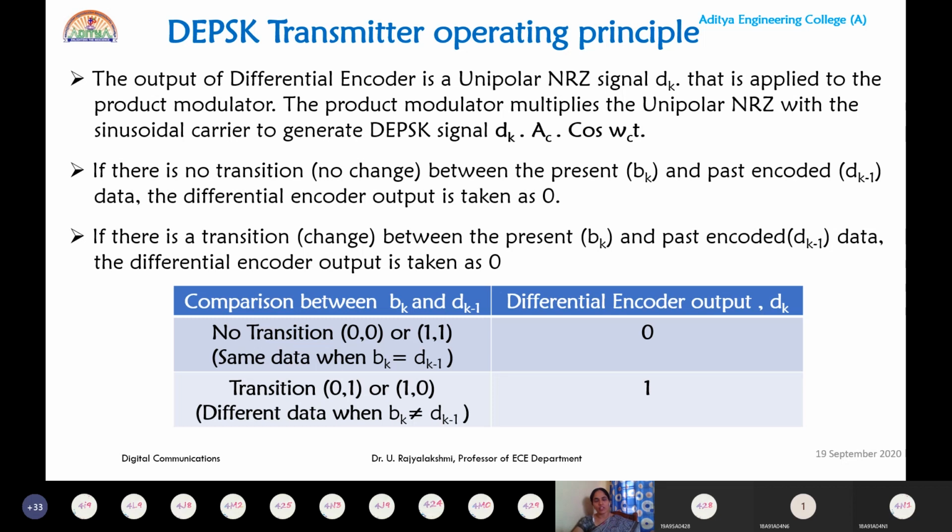So you may have a doubt about why we replaced it with the XOR gate, since we already have the XNOR gate. Because you can see the receiver. At the receiver also, we make use of one XOR gate to compensate for the XOR used at the transmitter. That's why an XOR gate is used at the transmitter section, and one more XOR is used at the receiver. You can see the circuit. So, is the DEPSK transmitter okay for everyone? Can we move further? Please, one of you respond.